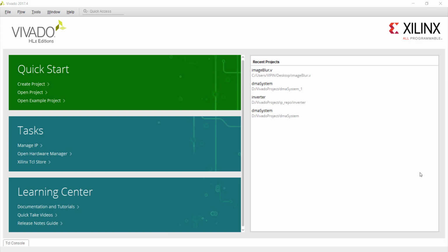So we are going to quickly see how to include these in your code. I will introduce a few of the IP cores, but a large number of IP cores are available from Xilinx. Either they are totally free, or for some of them you get a license only for implementation, but you cannot run them on hardware. You can go till implementation and simulate it, but you won't be able to generate a bitstream. For generating a bitstream, maybe you have to take additional licensing by paying. So different kinds of models are available, but of course all simple IP cores are available for free. First I am going to show you a FIFO.